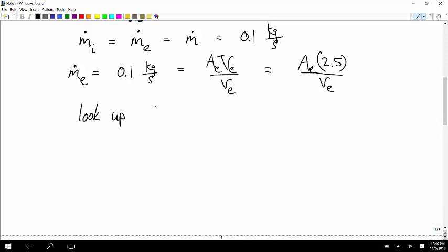It doesn't say anything about what the state of this material is, so we're going to have to look this up in 3 different spots. The fact that it gives a temperature and a pressure often suggests that it's not saturated, because it would only have to give us one of those if it was saturated. Which makes me think it's going to be in the liquid table.